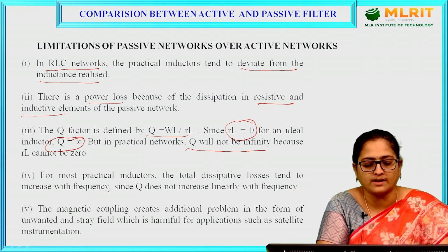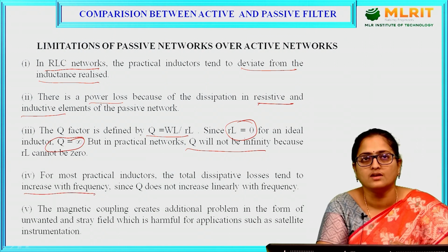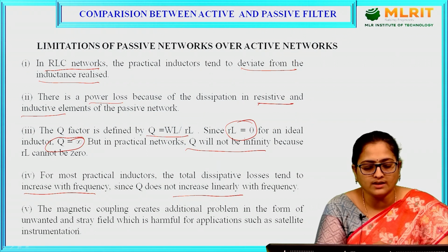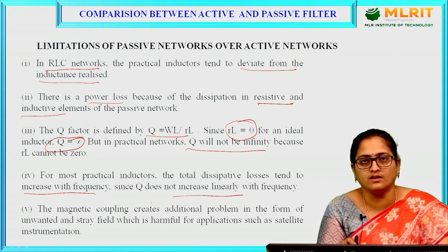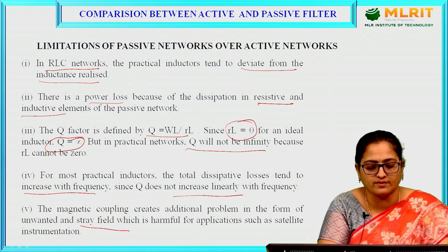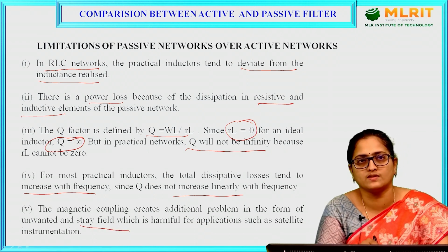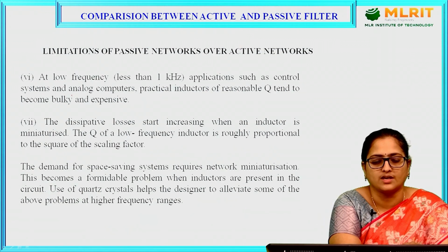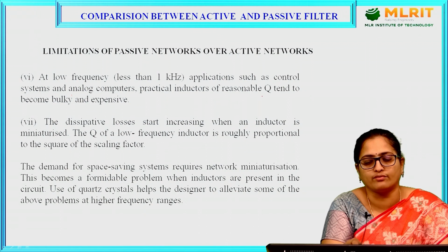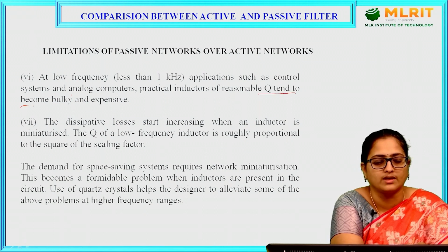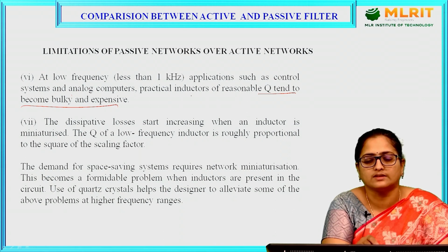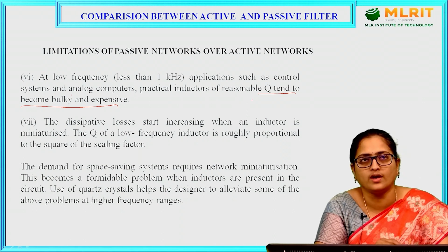For most practical inductors, the total power dissipation tends to increase with frequency, since Q does not increase linearly with frequency. Magnetic coupling creates additional problems in the form of unwanted stray fields, which are harmful for applications such as satellite instruments. At low frequencies, in control systems and analog computers, a practical inductor of reasonable Q tends to become bulky and expensive. As we are using an inductor, the circuit becomes bulky and also expensive.